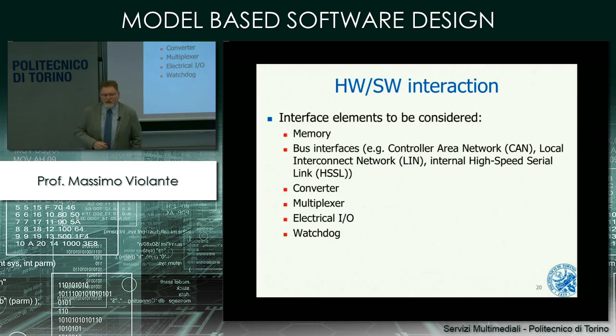As an example, one of the faults that we have considered in our analysis, think about the QA or the CTA, is that the microprocessor is broken and is not able to execute software. Then we said that out of that failure, we could have a hazard. Let's say we are not able to inform the driver of an incoming vehicle, or we are not able to close the speed loop to keep the safe distance from the preceding vehicle. These are examples of manifestation of the fault.